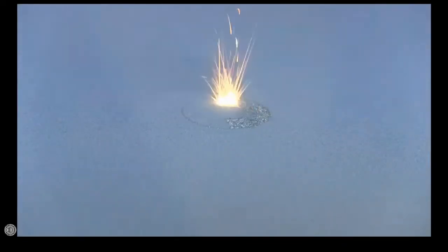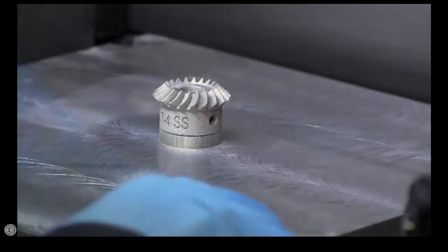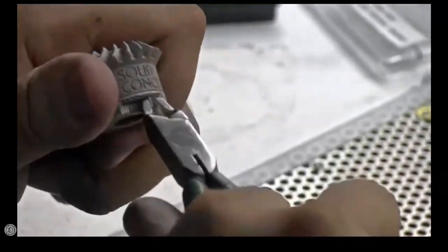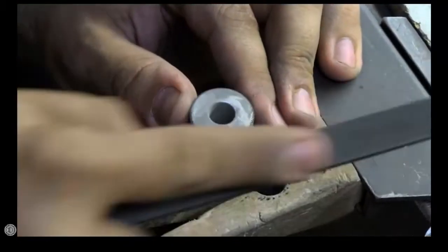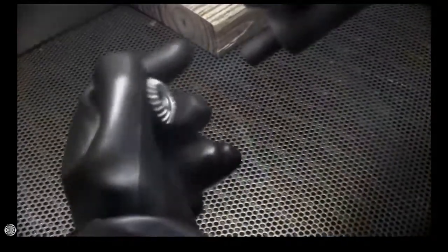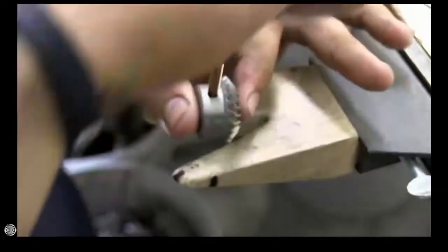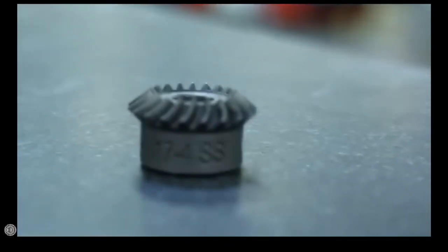As the part is built, support structures are added to give supplemental strength, fine features, and overhanging surfaces. The completed part is then removed from the base plate and treated with an age-hardening heat process to further harden the part. Any support structures are also removed at this time. With numerous surface treatment and hand polishing options available through service providers, DMLS parts can be used in highly cosmetic applications. Typical uses for DMLS include tools and manufacturing aids, small integrated structures, dental components, surgical implants, and aerospace parts.